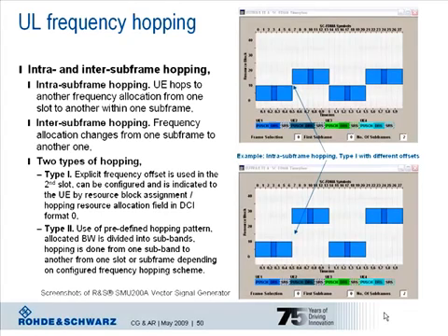In LTE, there are two modes of hopping: intra- and inter-subframe hopping. Hopping at all is an optional feature, but it is an approach to overcome possible frequency selective fading on the radio channel. When intra-subframe hopping is configured, the UE hops from one resource block allocation to another one within one subframe. This means in the first slot the UE would transmit, for example, on the lower edge of the spectrum, in the second slot on the upper part of the available spectrum. Inter-subframe hopping means now that the UE changes the allocation from one subframe to another one.